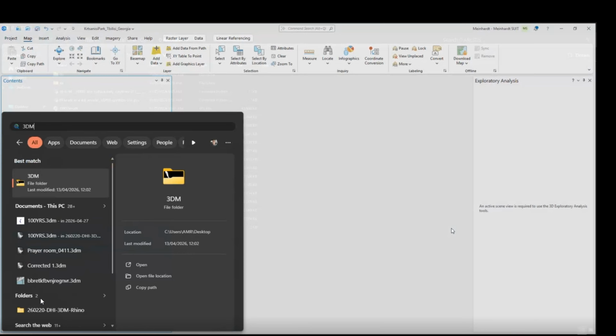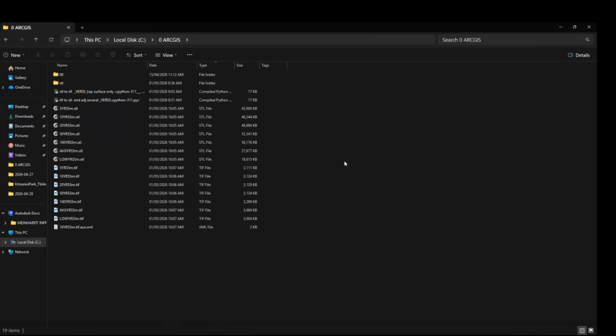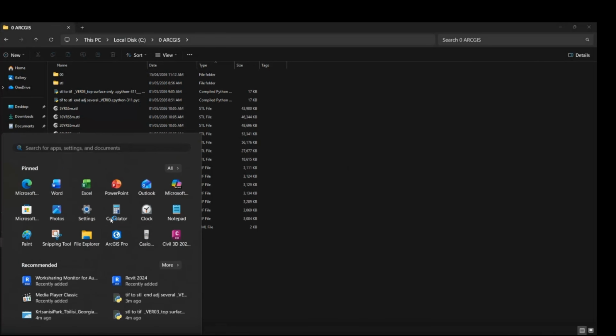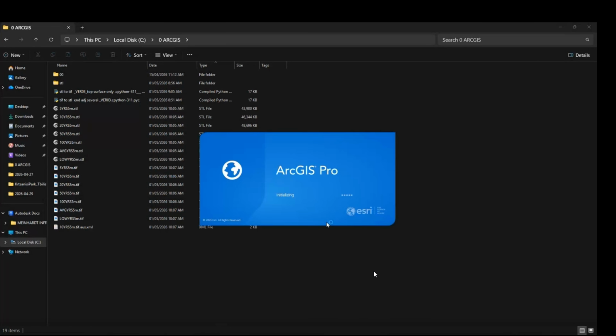There are several options. You can use 3DM to shift it manually, or you can use QGIS to shift the TIF using the georeference option. Just take 1 point from the 0,0 location and 1 point from the actual location, and the entire TIF will be shifted.